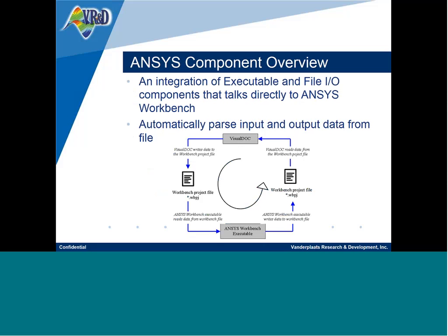In the previous version, the user could use the executable and file I/O components to couple ANSYS with VisualDOC. But the user needed to set up the connection between the executable and the file input and output, and also define how to extract data from the file input and output. In the new version, the ANSYS component allows the whole process to be done automatically.